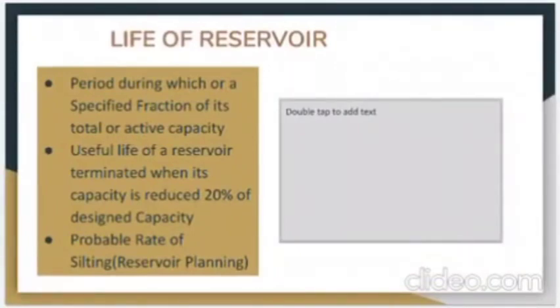Life of reservoirs. The ultimate destiny of a reservoir is to be filled with silt deposits. To allow for silting, a certain percentage of total storage is usually left unutilized and is called dead storage. However, as time passes on, more and more silting takes place, and the